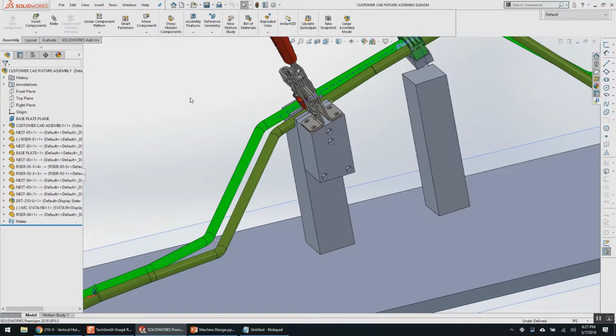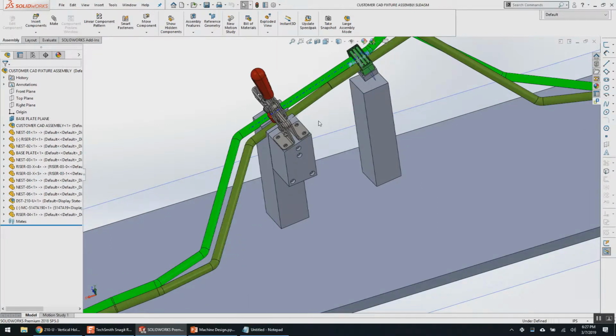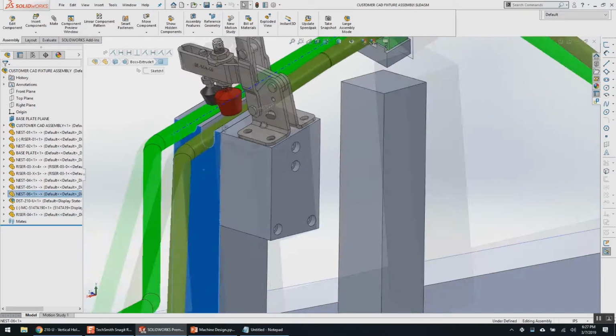Yeah, so general machinist handbook rule of thumb is double the diameter will give you maximum thread holding. Any more than that is unnecessary. Any less than that, then your threads will rip before your bolts. Aluminum being softer, sometimes 3 times is the preferred method, or for plastics. But generally any mild carbon, steel, stainless, whatever, 2 times is kind of your golden rule there.